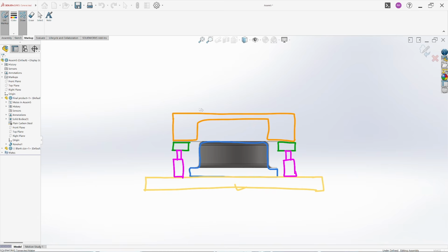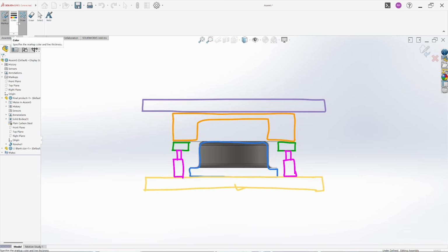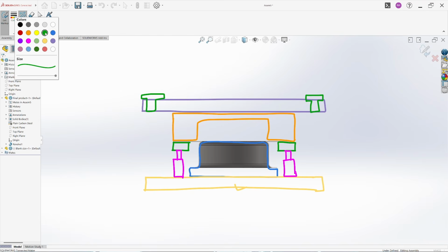Now our die will also be mounted over a plate, a pressing plate, and the pressing plate will be attached to our hydraulic cylinder. But first let me draw a guide here. So there will be a bush over the pressing plate, right? Something like this. I know this sketch is not good, but just assume these will be our bushes, and there will be a guide.